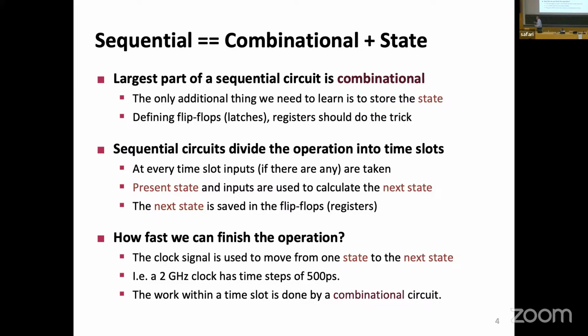We do calculations, calculations, calculations, and at some point, even in the worst case, even if my calculation is very difficult, remember we were propagating carries back and forth, all of these things have happened, I gave them enough time, and now we will tell the state element, memorize it. When we talk about synchronous circuits, not asynchronous, this memorization period, this time where the state holding elements do the memorization trick, is fixed. We already have defined, for example, we say we will use a 2 gigahertz clock.